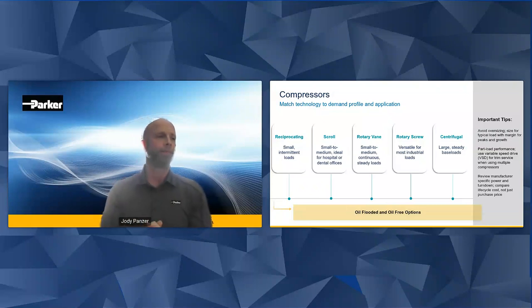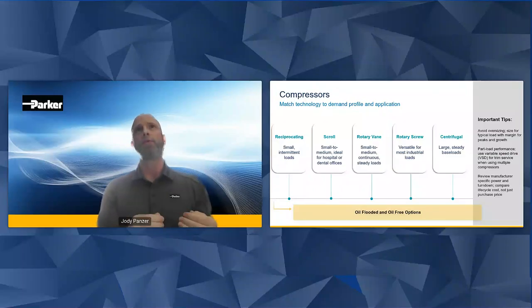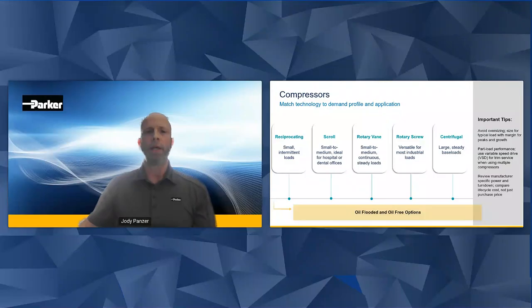So you need to avoid this in sensitive applications: healthcare, food and beverage, semiconductor, pharmaceutical. There are food-grade oil options available, but note that those will degrade faster and require more maintenance and more oil changes. Oil-free, on the other hand, can be used for those sensitive applications.